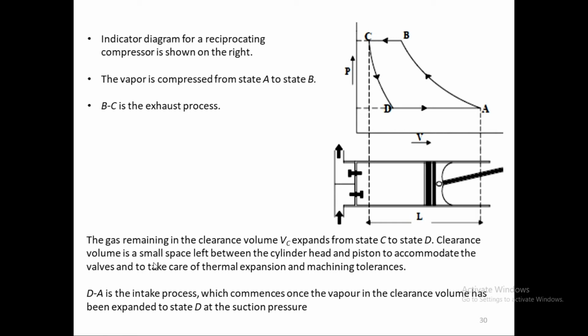Clearance volume is a small space left between the cylinder head and the piston to accommodate the valves and to take care of thermal expansion and machining tolerance. So this gap has to be left there because of the tolerance, because of the machining limitation, and because of these valves also. That's why it is necessary to leave this much clearance volume here.